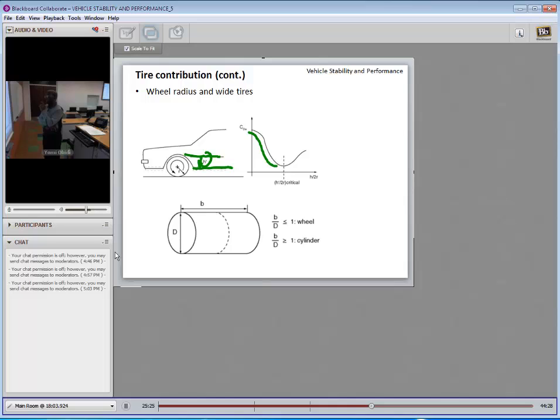The larger H over 2R is, which means increasing the height of this opening, okay? When you increase it up to a point, you have drag reduction. After a while, if you increase it beyond that, it really doesn't create improved performance.